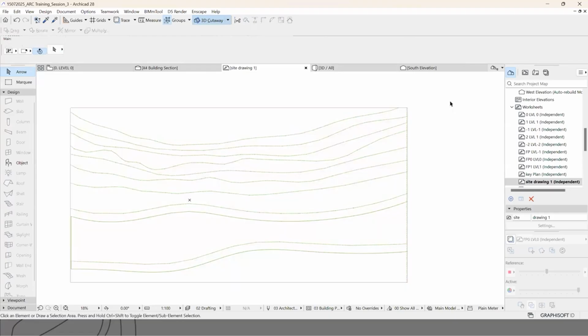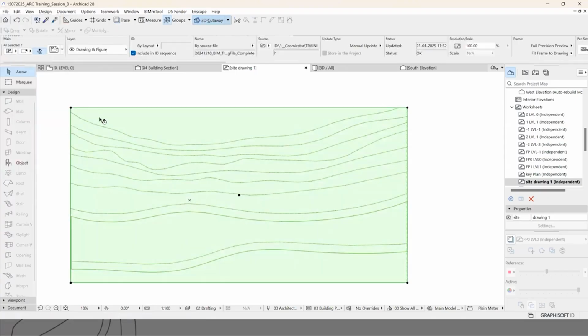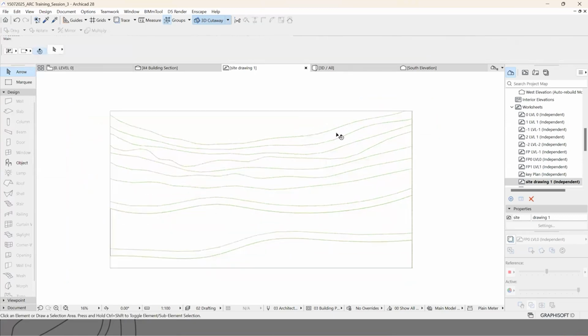So if the file is properly done, like using polylines and not broken, you can use the XRF method itself to bring them in so that it is going to be easy for you to work. But this particular CAD file is actually broken into different segments, so we may not be able to use the magic wand tool properly. So that's why I'm approaching it this way.